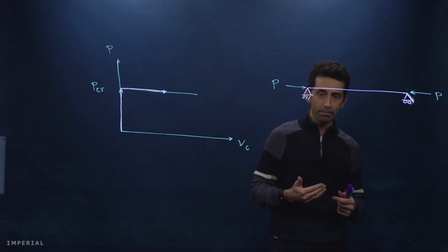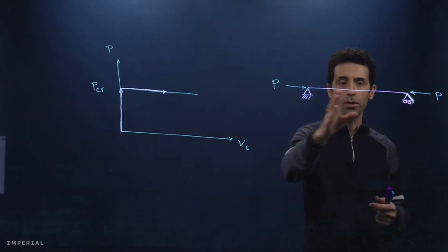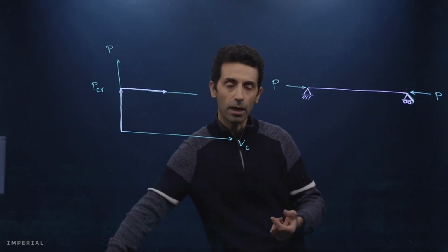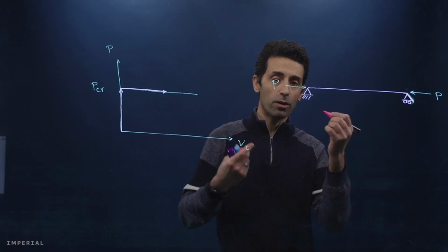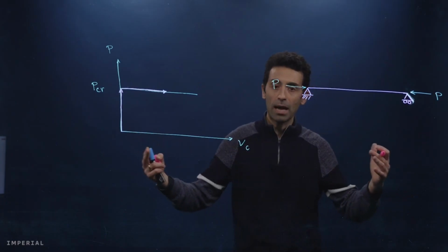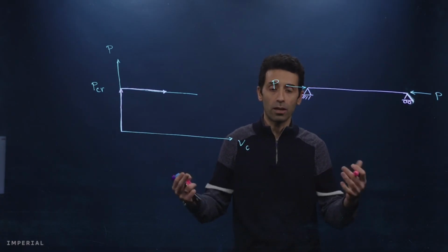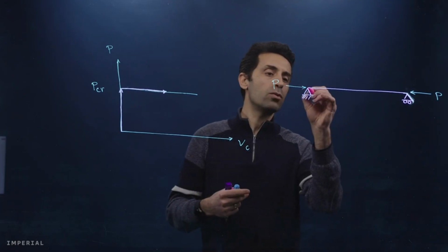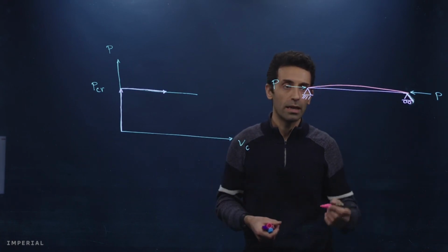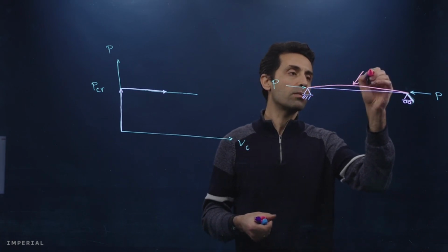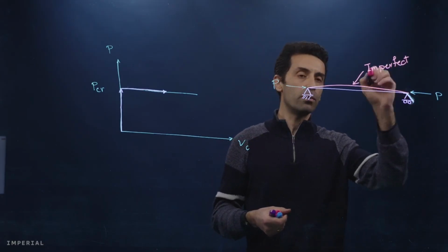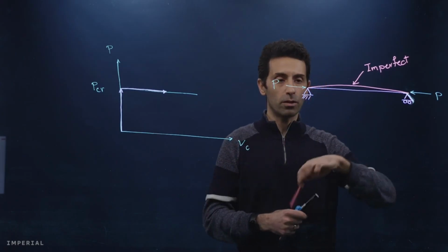But in reality, our structures are not perfect, so the beam is not straight like this. It might be slightly bent before you even apply the load. Like the demo that I just showed, in that demo, that aluminium beam has been put under axial load several times and it's already a little bit bent. So the actual geometry could be slightly different to that straight line. And this is the imperfect geometry. This one is the perfect geometry.